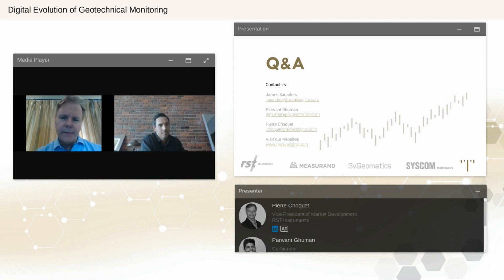ISO 18654, the new spec, the standard on geotechnical monitoring that covers piezometers, inclinometers, and so on. They specify a 24-hour stability for the sensor itself. So not the whole string of IPIs or shape arrays, for the sensor itself. And I think it's a value something like 0.01 degree over 24 hours. So that's to qualify the sensor itself.